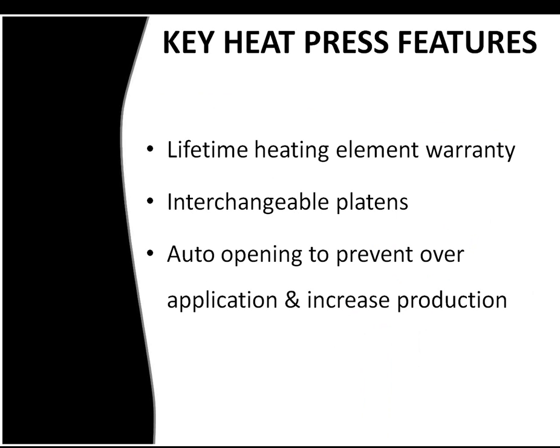And some features of heat presses that you're going to want to ask different manufacturers for is warranty. And warranty is really super important. You always want to make sure that there is a lifetime heating element warranty. The heating element is the most important component of a heat press because without even heat, you're going to have inaccurate applications. So you want to make sure that the warranty covers a lifetime on the heating element. That's the most important part. You could try to finagle some of the other things that may go wrong with the heat press, but there's no way you're going to work around heat.